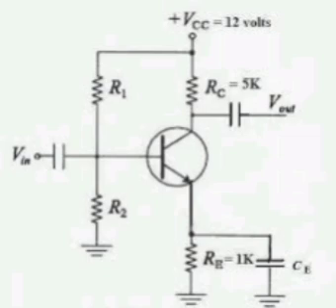The circuit diagram of shunt type ohmmeter shown in figure consists of a battery in series with an adjustable resistor R1 and a basic D'Arsonval movement meter. The unknown resistance is connected across terminals A and B, parallel with the meter. In this circuit, it is necessary to have an on-off switch to disconnect the battery from the circuit when the instrument is not in use.